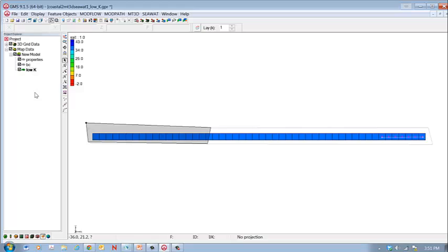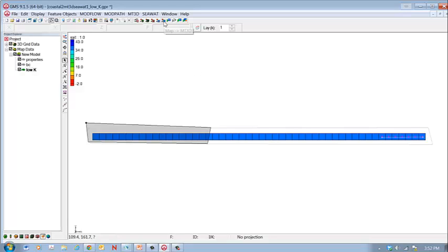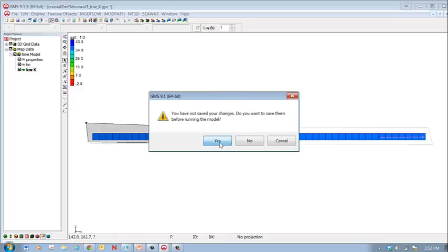However, what I've found is that if you go back and modify the MODFLOW simulation, particularly if you switch from transient back to steady state, then it will crash immediately, virtually every time. So we're not going to go back and mess around with that. Okay, we can just go ahead and map this. We need to map it to MODFLOW and MT3D, and then run SEAWAT.